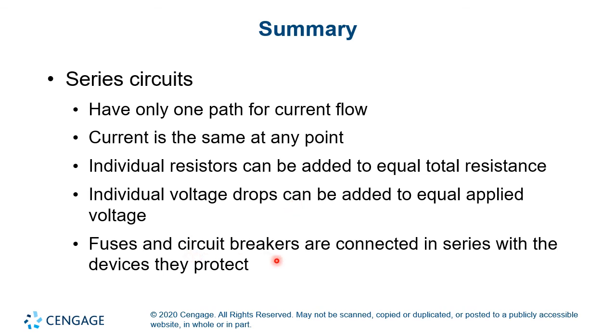An example of a series circuit is any circuit that has a fuse or a circuit breaker. They must be connected in series because of the way we want them to function. If that fuse is blown or the circuit breaker is activated, we want to make sure that no current can flow to the device, so it's protected. In general, the whole idea of these is to protect them from higher voltages or higher currents than they are able to withstand.